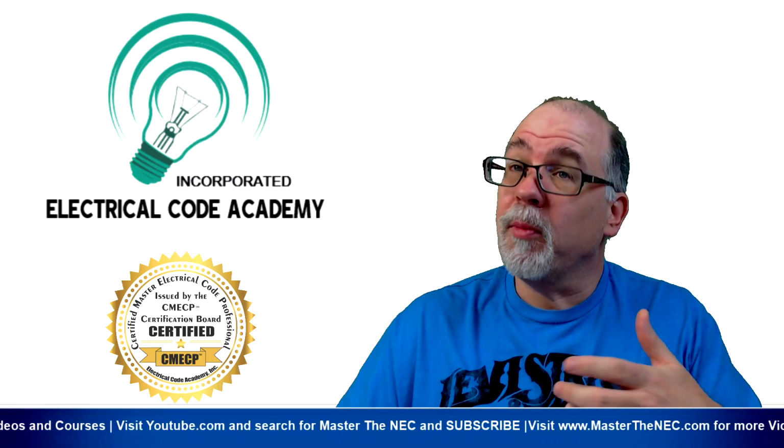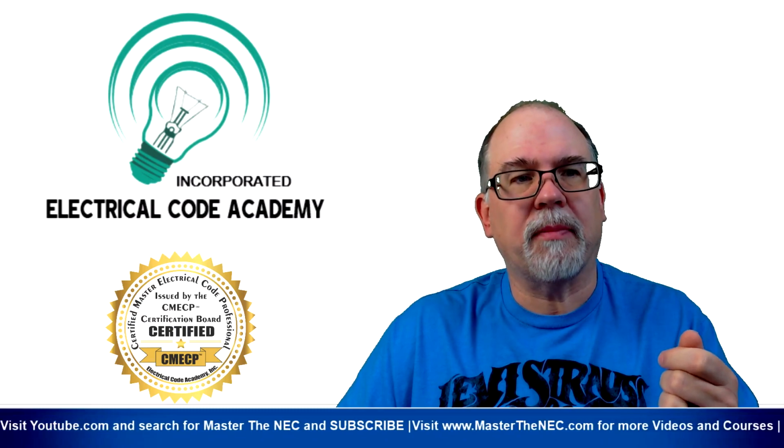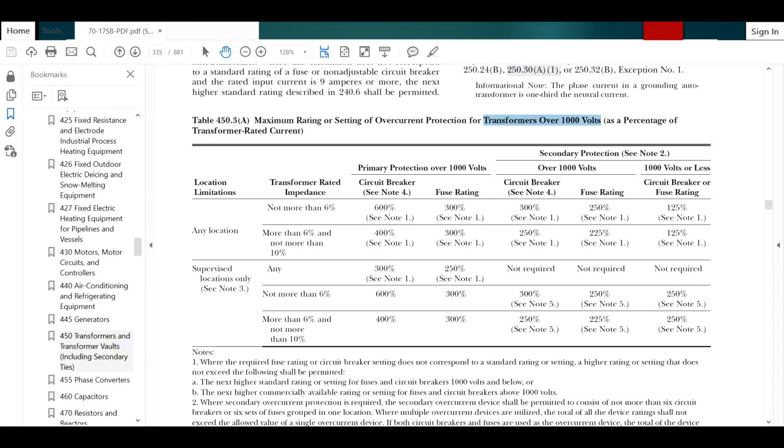Okay, so now we're moving on. We're getting more advanced. We're making sure that we size that overcurrent protection device properly. So let's go look at the code a little more and see where we're at. So now, if you were having to deal with transformers over 1,000 volts, then you would be in 450.3(A). Of course, in our example today, we are not. But here it kind of gives you a layout of this table.